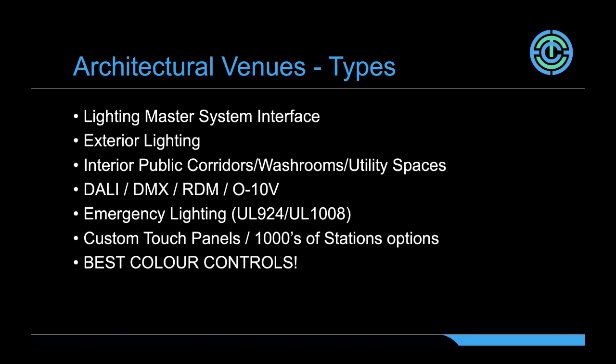Again, in one of our sessions previously last week, we talked about emergency lighting. And all of our power control devices are UL 924 listed, and our mains emergency power switching or upstream power switching devices are UL 1008. And again, if you get an opportunity to go back and look at that emergency power discussion, it would bring to light, no pun intended, some of the key components of what's needed to think about in emergency lighting, egress lighting.